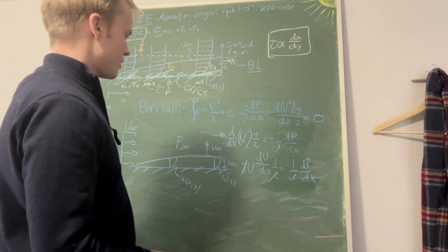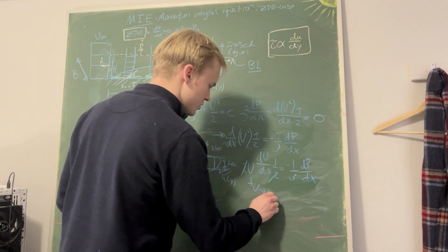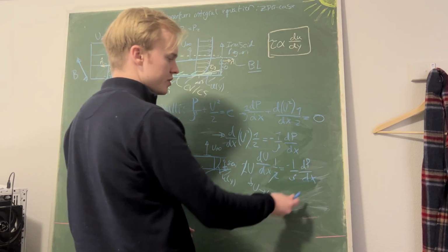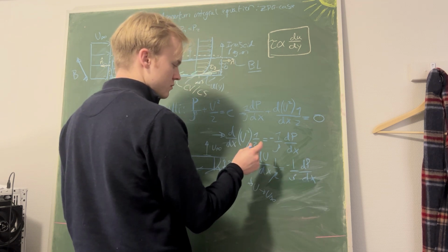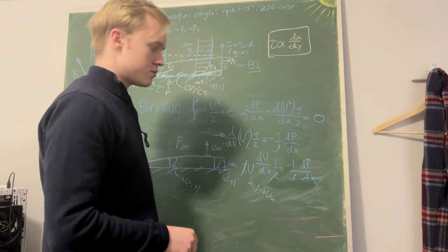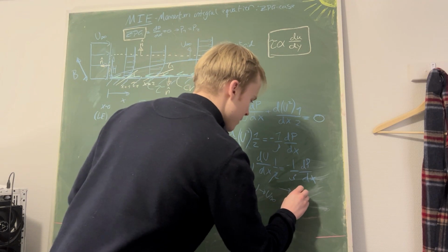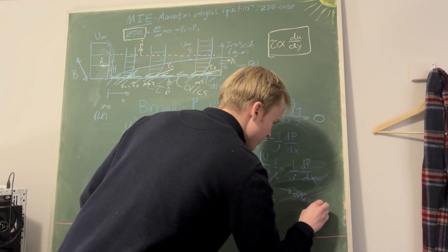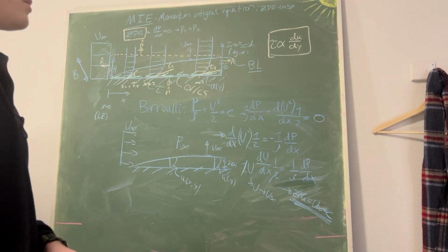And then we see here that over the boundary layer, if our u goes to our u infinity, we end up with the same. And the same being that when we set a ZPG, the dp/dx is going to be 0. Well, u du/dx is going to be 0. And we integrate this again as we did with the Euler. It's still going to prove that, for ZPG, the u infinity is a constant. That is the main point from this.